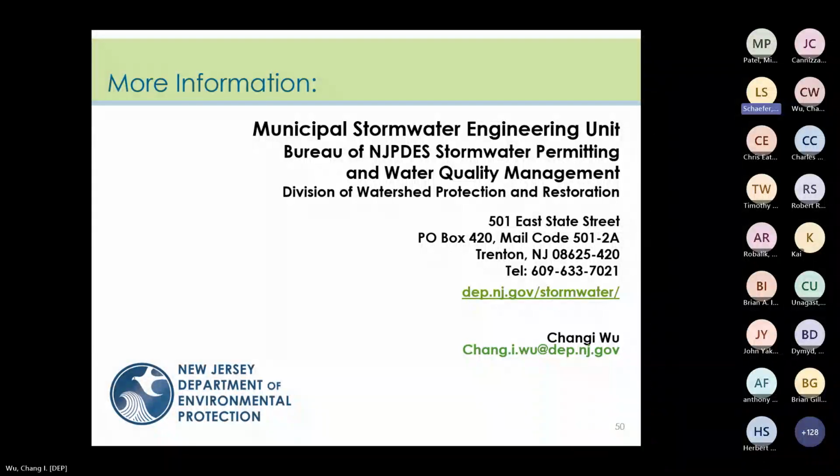Your slide also directs people to go to example 5-9 from chapter 5 to see the sizing calculation for the MTDs. And you will see now in the newer MTDs that are on our website, the certification letters have switched over to using the NRCS methodology rather than the no longer allowed rational method to calculate the flow rates.